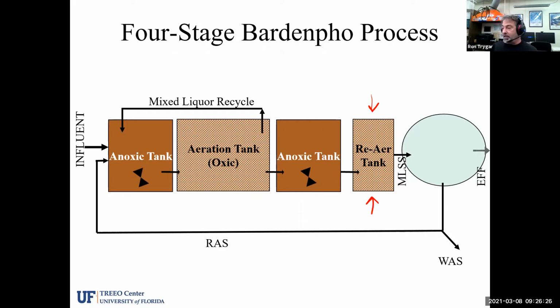So what's the big deal about the re-aeration tank? Well, first off, we're not going from the anoxic tank directly into a clarifier, where there would be the potential for more denitrification to take place in that basin, or to go even anaerobic or even septic down in the sludge blankets.